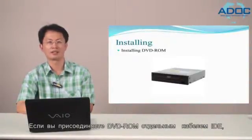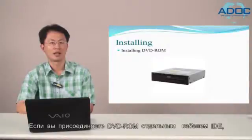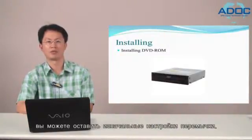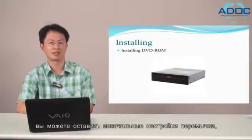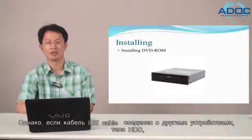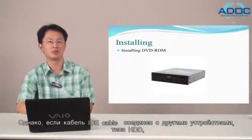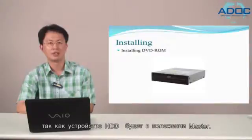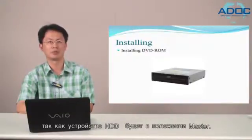If you are connecting the DVD-ROM on a separate IDE cable, you can leave the jumper setting at master. However, if you are sharing an IDE cable with another device like an HDD, then you will have to set the jumper to slave, as your HDD would be set to master.